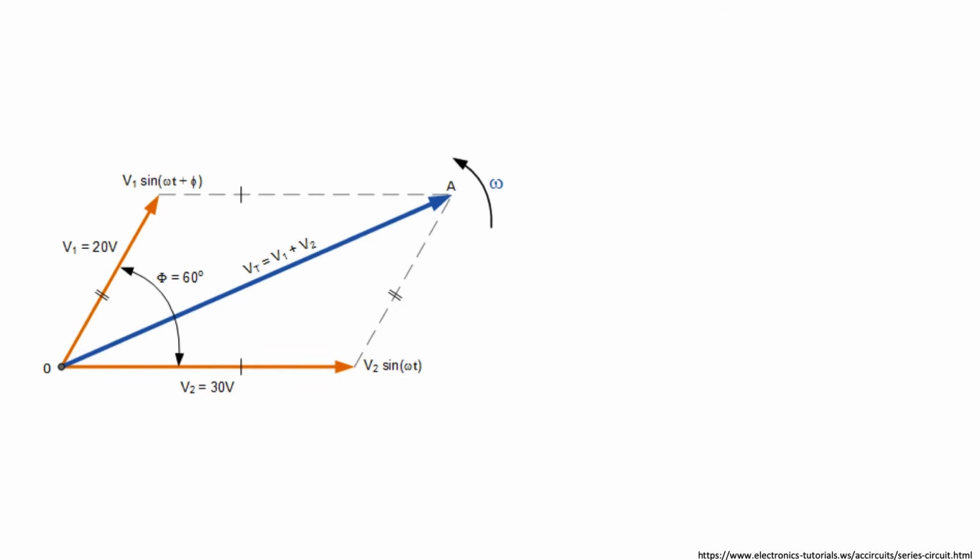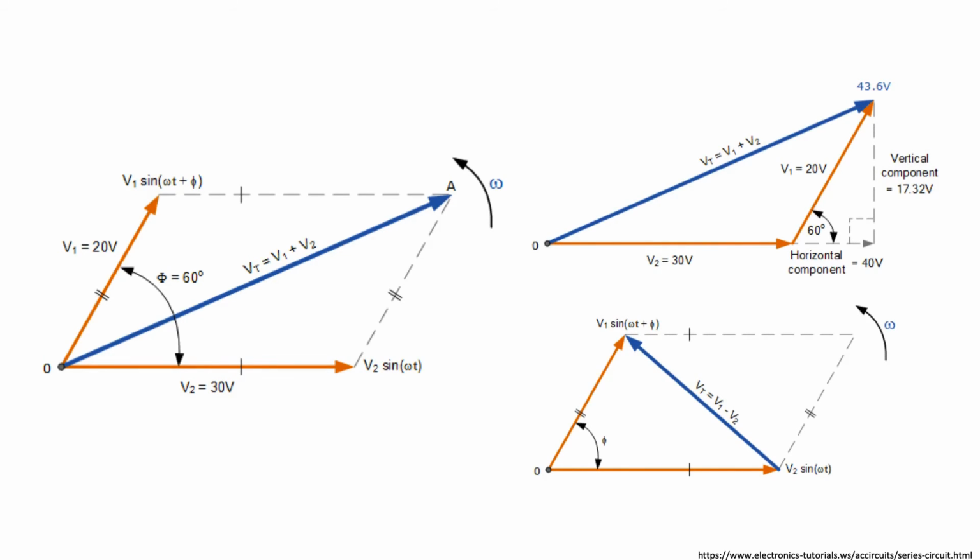Graphically, we would add the phasors the same way we add vectors. That is, we either draw the resultant phasor from the parallelogram method, or we connect all phasors head to tail, and the resulting phasor would be the phasor corresponding to the source voltage. Again, the reason for using this and not simply using algebraic addition or subtraction is because phasors are always expressed in terms of the amplitude and the phase angle, and phasors are complex numbers.